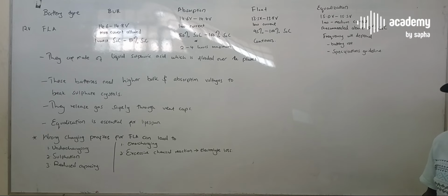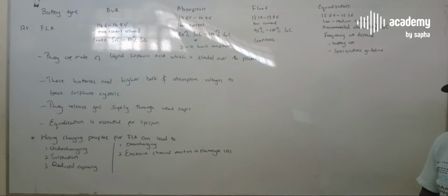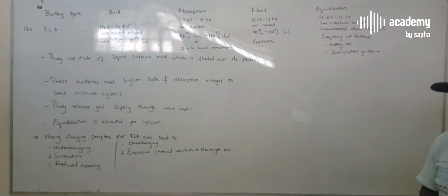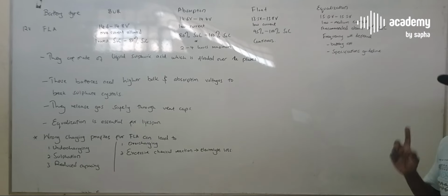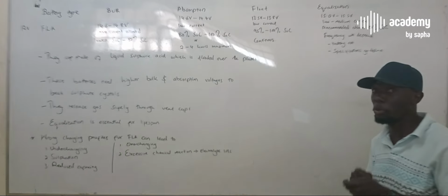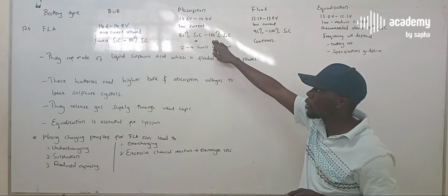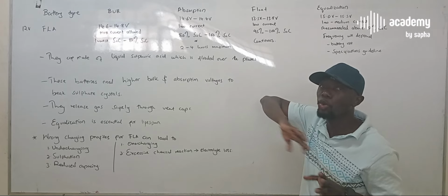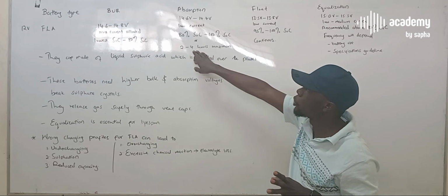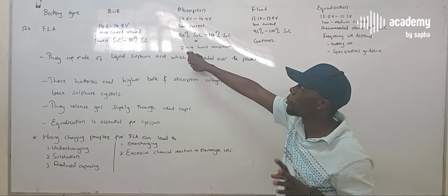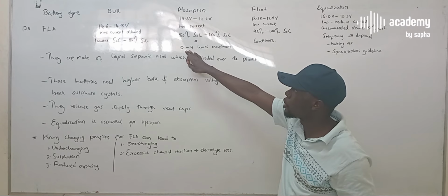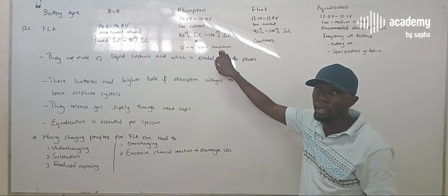So you yourself can do a monitoring. You can have a separate gadget to monitor the voltage levels, or there's a calculation that, when you combine a few components, can tell you the battery's SOC. So in any case, if you don't want to go through all that, you can at least manually program your charge controller to do it for 2 to 4 hours maximally.